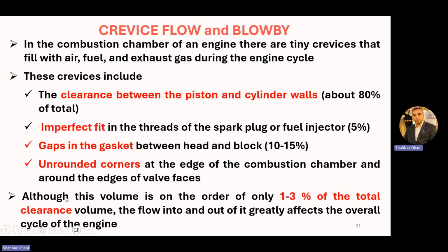Although this crevice volume, or gap volume, is on the order of only 1 to 3% of the total clearance volume, and the clearance volume is already very small, the flow into and out of it greatly affects the overall cycle of the engine.